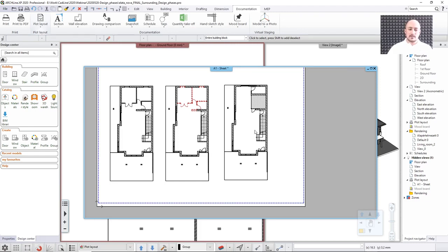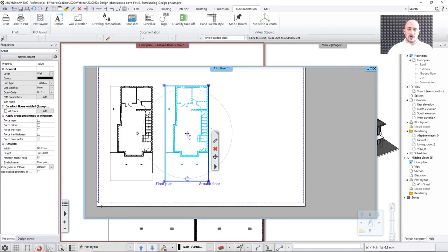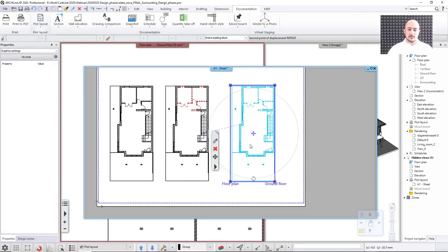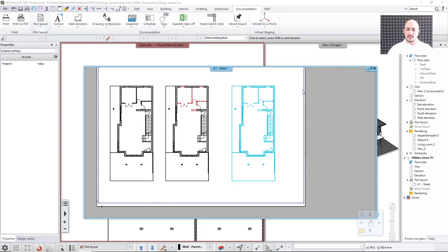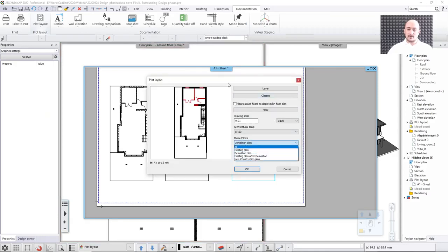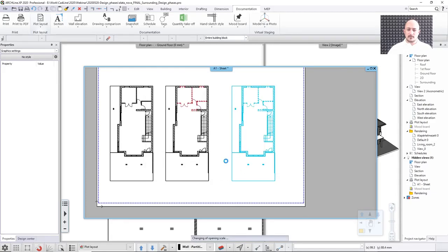Even further, you can actually just do this as well, remove this one and use this move marker. You should not use Ctrl+C, Ctrl+V. You should use the move marker and use the move or copy, because this behaves a little bit differently. If you do that, this will make a dynamic instance of this one. And then you can go to the properties again, and you can just change the same thing. So you won't copy a group, but you will copy a dynamic instance of this one, and that has all the same properties. So you can just do the same thing. So I think I pretty much covered this part now.